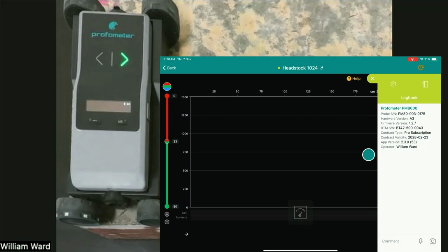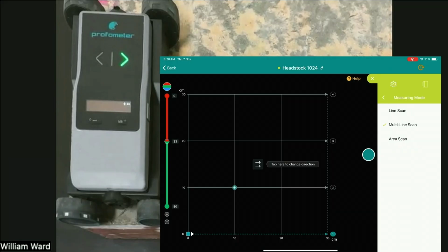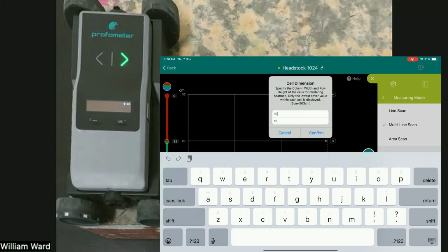So just to show this in action again, multi-line scan, so we see it's a single line lined up over the reinforcing. And I give it my exact spacing. Now the spacing is good because if I've got 200mm bar spacings, that's probably my grid. Unless maybe I just define my grid by my corrosion grid, then I'd do my corrosion grid, but I'd still try to, as much as possible, keep in between bars when I take each line. We want to always account for interference. We always want to know that bar layout and account for interference using the tool.